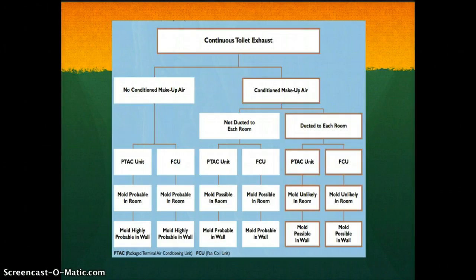Building commissioning should include the following concepts to reduce the possibility of moisture and mold problems. A technical peer review should occur during the design phase, identifying issues that may lead to moisture and mold problems. To achieve this, someone with the requisite skills may need to be called in because the traditional commissioning agent may not have the requisite skill set to conduct this type of analysis.